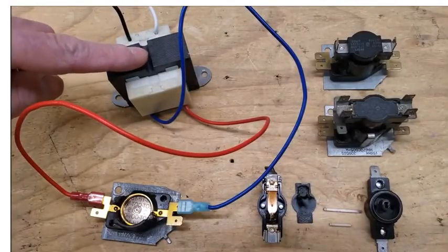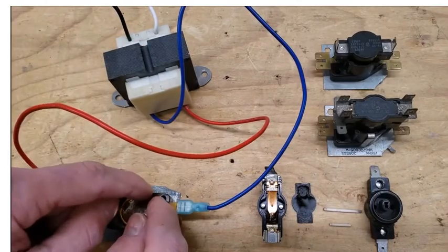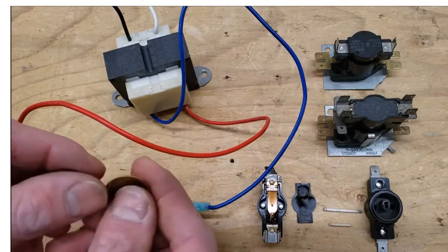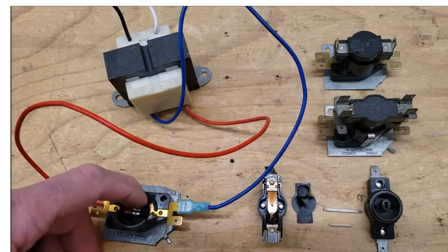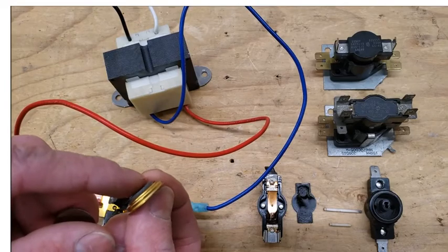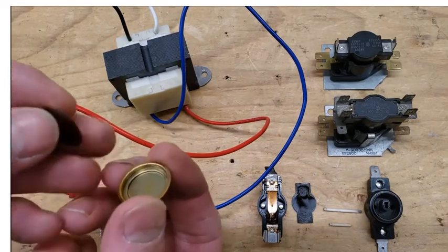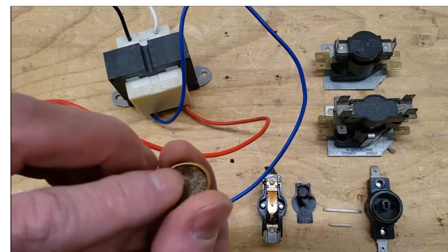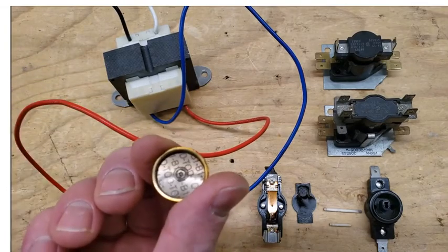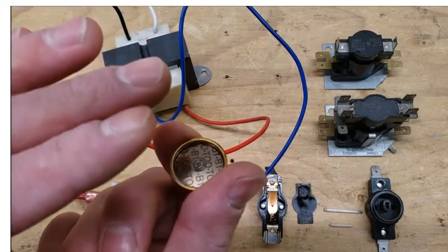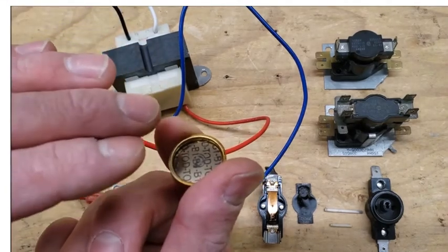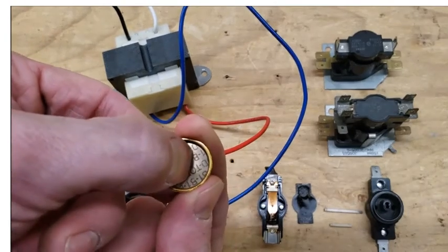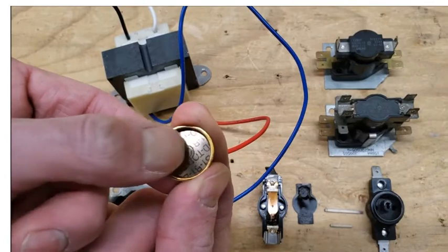So this transformer is not powered. Even though it's connected, it's not powered. I just want to go ahead and show you what this little plate looks like and the thermodisc. So you have your 24 volts coming over to this piece of brass, and it's touching this right here, which is your heater for your pan. And then this little thermodisc is actually pointed upwards in the middle right here and just sits right in the pan. As it heats up, it's going to make a noise. It's going to go boom, and it's going to tilt this part inwards. Okay, so I can press it in by my hand just like that.